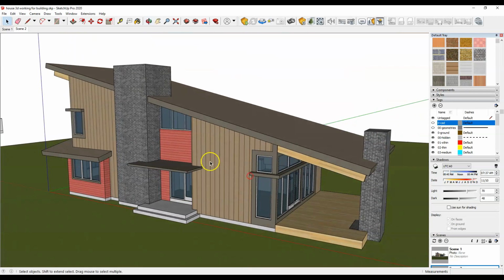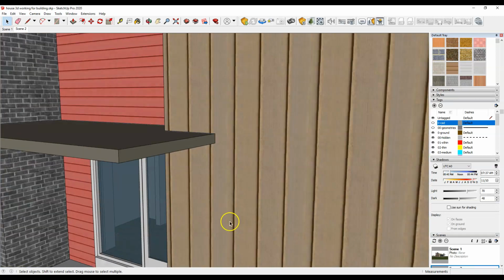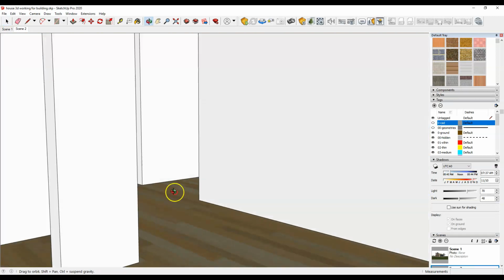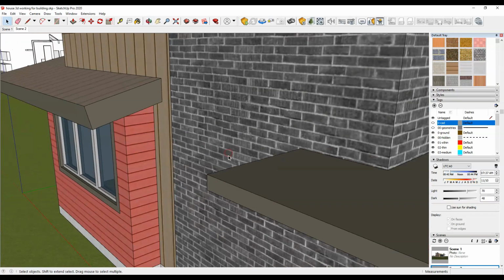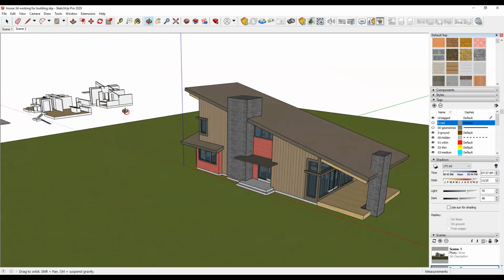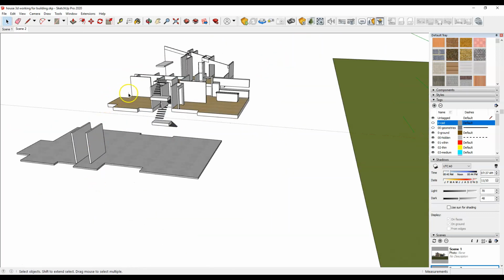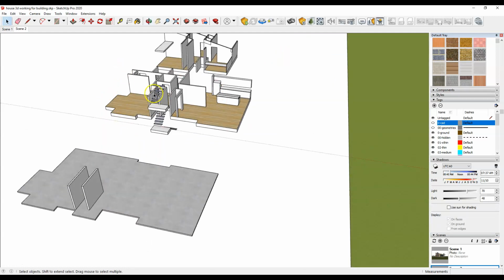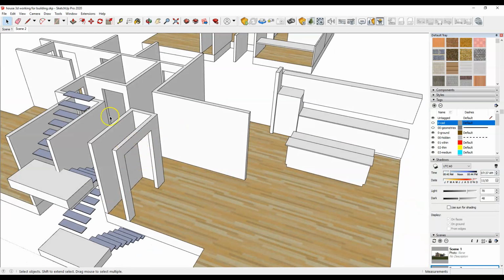Now, to build inside this house in most 3D modeling software, it's a bit difficult to go in and draw. I can come in, but then I'm so tight in here that it's really difficult to model. So one thing to do is just have the CAD floor plans out here and model right on top of them. I modeled the floor, I pulled it up, and then I modeled the interior walls. I did the interior walls exactly like the exterior walls. So before I drew any doors, it was a solid surface.